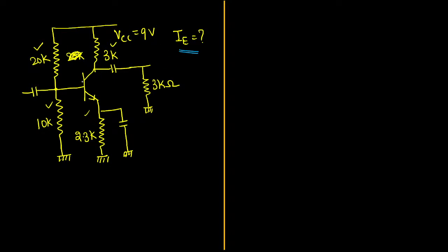If you observe the base side, we have two resistors connected to the base terminal. If you observed our previous lecture, I was clearly telling that whenever you observe this kind of connection in your base side, what do we have to do? We have to Thevenize the circuit. That is the first step before proceeding further. How will you Thevenize? We have to apply Thevenin theorem here.